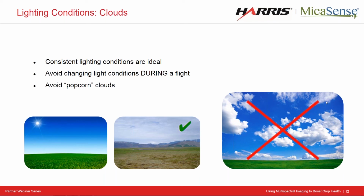But really what you want to avoid are severe changes from shadow to sun, like you'll see in a cumulus cloud situation, kind of like what we see on the right-hand side of your screen. That's going to create sharp changes in light to shadow that are too extreme to completely eradicate in data processing. So sometimes it causes anomalies in your data.